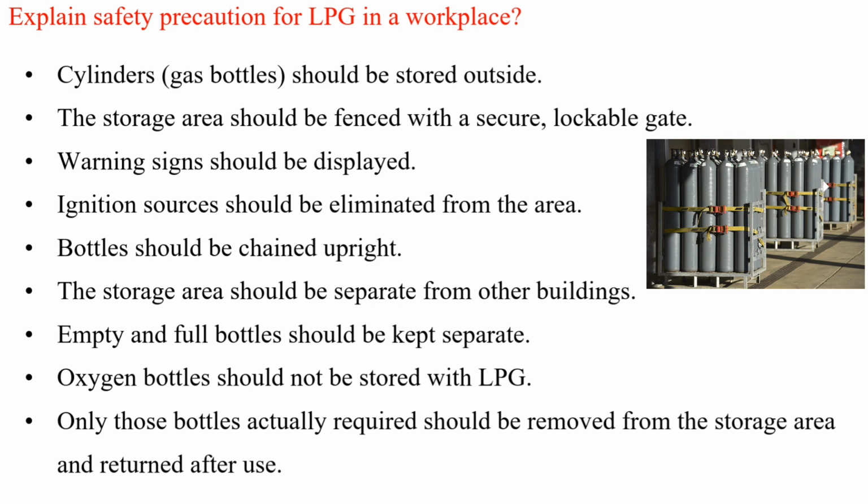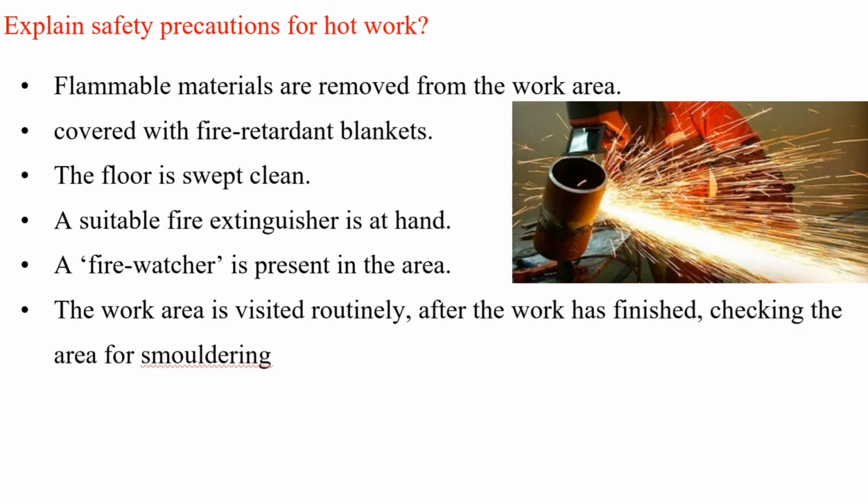The storage area should be separate from other buildings. Empty and full bottles should be kept separate. Oxygen bottles should not be stored with LPG. Only those bottles actually required should be removed from the storage area and returned after use.